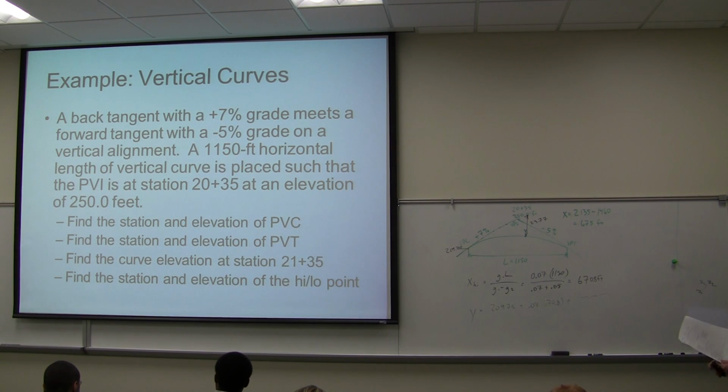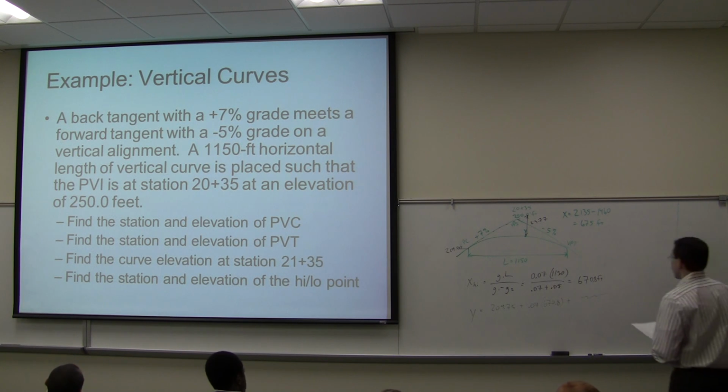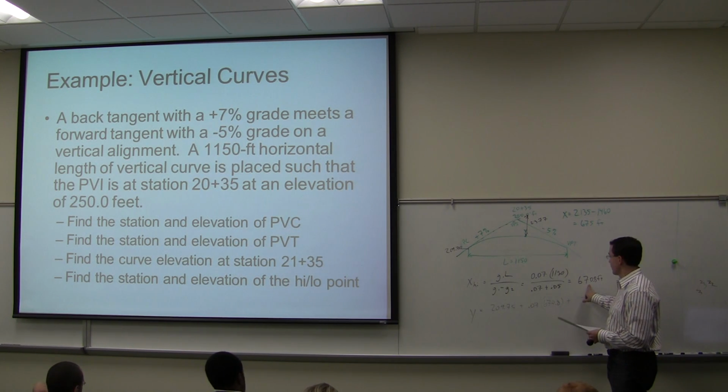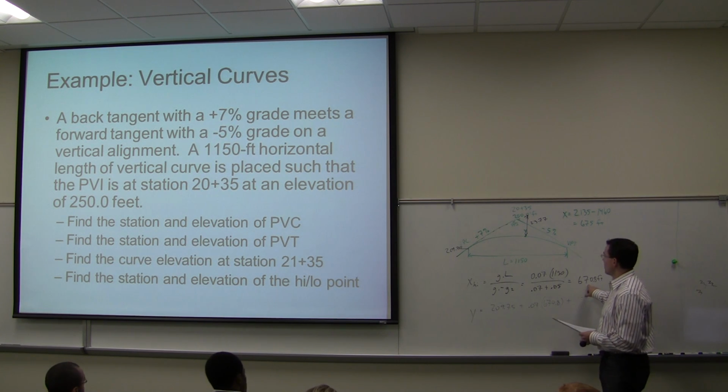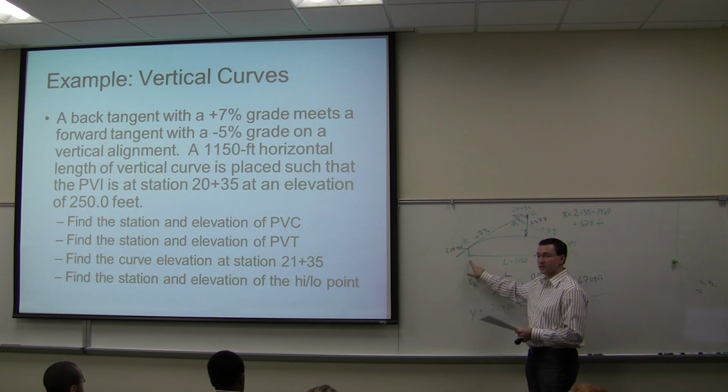So questions on vertical curves? So we found the horizontal distance in the x high. If we add that to our VPC, would that be the station of our high point? Yes, if you add the VPC station. Yep. Okay.